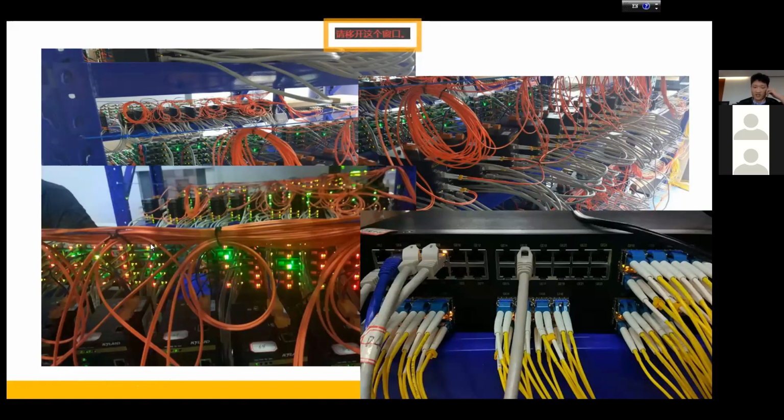Finally, we found that several controllers had packet loss in the network, and we did the troubleshooting. We found it was related to the bandwidth and the network design. You can see that these optical fiber ports are for the downstream links, and this copper port is for the uplink to the server. Both of these ports are 1 gigabit ports, the same bandwidth for the lower layer and the upper layer.